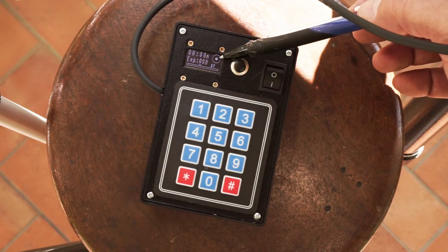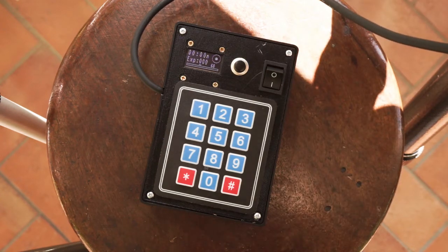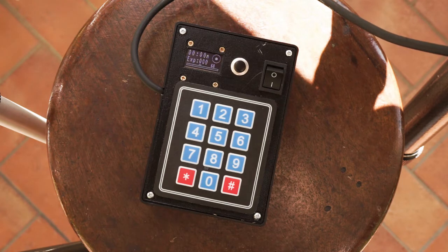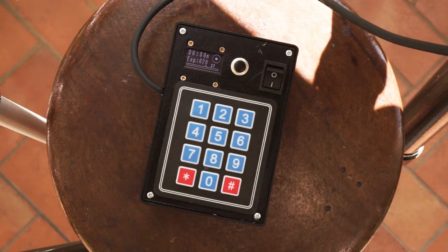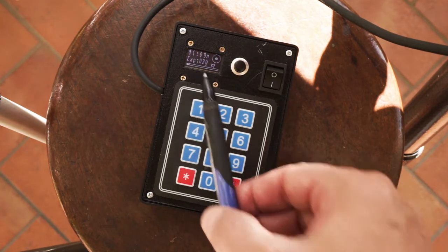If the UV is very strong, this inner circle will fill the external one, and if the UV level is very weak, it will be just a dot. If I key, for instance, 20 and press star, it tells me the time needed for this 20 exposure. If I say, okay, let us do a test strip using this 20 as a level of exposure, then I press the pound sign. Now you see it started a countdown in time, and the progress bar started to move.